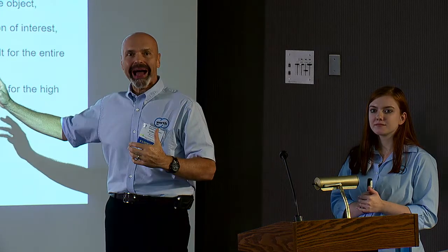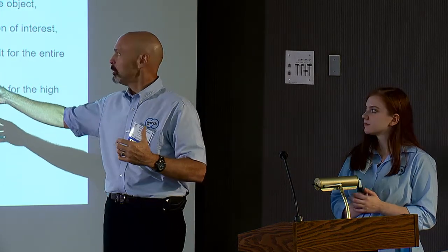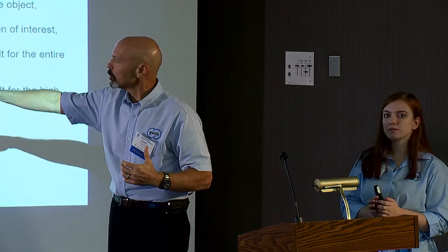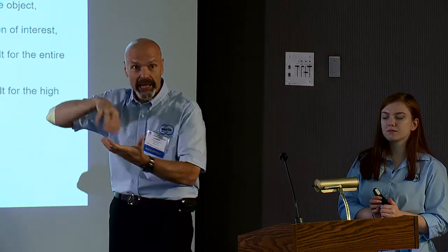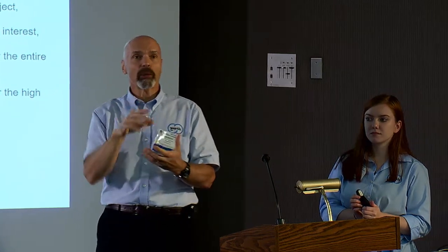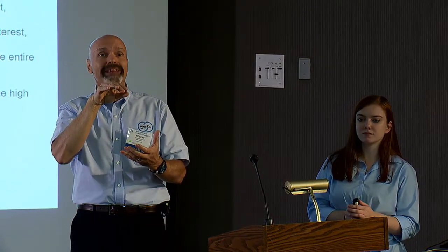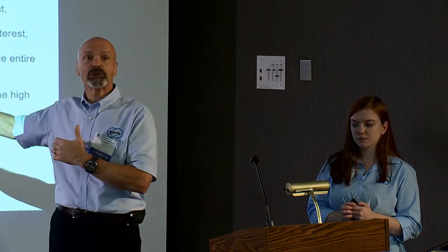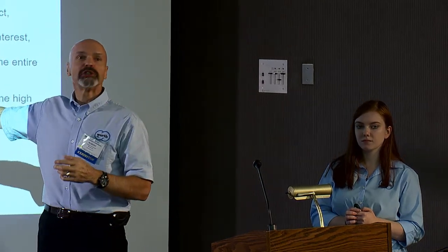But like Jacqueline says, without a coordinate system, without being able to put that one separate little blade into a larger coordinate system of the entire blade head, it doesn't mean anything. In order to do evaluations or measure anything worthwhile, to be able to see radiuses or where that is in relationship to the rest of the part, you need to do just a quick overall scan of the part. You can create an XYZ zero point, planes, cylinders. Now you can go in and you can measure things.